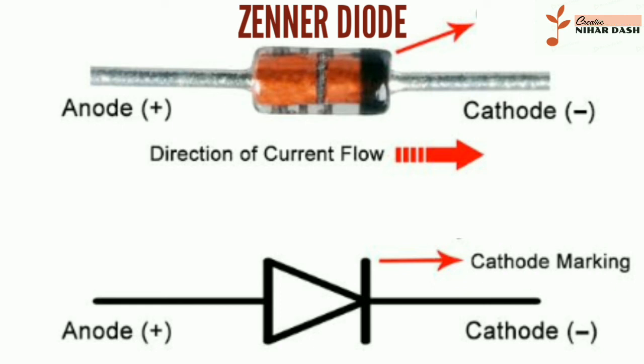Characteristic of Zener diode. The V-I characteristic graph of the Zener diode is shown in the figure below. This curve shows that the Zener diode, when connected in forward bias, behaves like an ordinary diode. But when reverse voltage is applied across it, and the reverse voltage rises beyond the predetermined rating, Zener breakdown occurs in the diode. At Zener breakdown voltage, current starts flowing in the reverse direction. The graph of the Zener breakdown is not exactly vertical, as shown above, which shows that the Zener diode has resistance. The voltage across the Zener is represented by the equation shown below: V equals VZ plus.